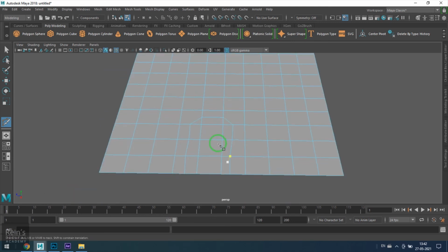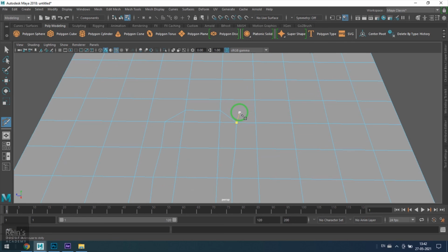Now at every turn, and this is a very common combination, you get a triangle and a pentagon, a five-sided face. It is very easy to fix. This triangle has to be split in the middle, and then in the opposite corner just connect it. Now I move the point so that the shape would be much clearer. Now the combination of triangle and pentagon is gone. Now I got a combination of three quads.